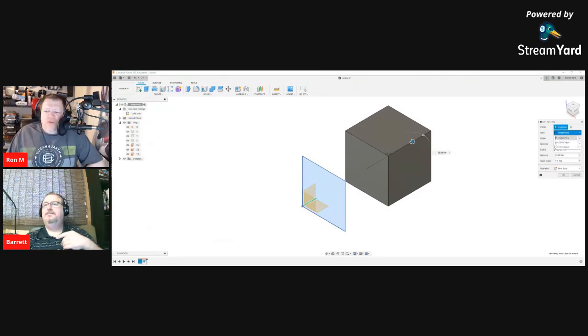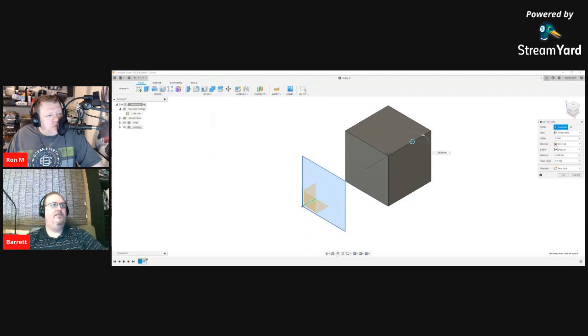So where does someone find that option that you just turned on? The plane was in the model tree view over on the left hand side here. I dropped down the origin and clicked the visibility button here for the origin. So that made the origin visible. And the other thing that's happening here is the sketch is visible. Because the sketch is selected, it's showing the initial sketch.